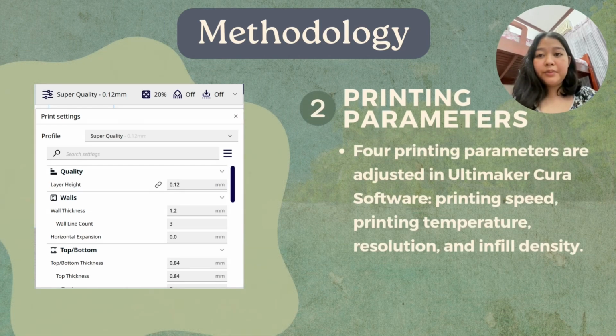Next, we will discuss the printing parameters. Four specific parameters were adjusted using Ultimaker Cura: printing speed, printing temperature, resolution, and infill density. This approach allowed us to assess the impact of printing speed on print quality, structural integrity, and conductivity. We varied the printing temperature to observe its effects on layer adhesion, material flow, and overall conductivity. Resolution was adjusted to evaluate its role in achieving fine details and smooth surfaces. Finally, we manipulated the infill density to explore its impact on structural strength and overall conductivity.